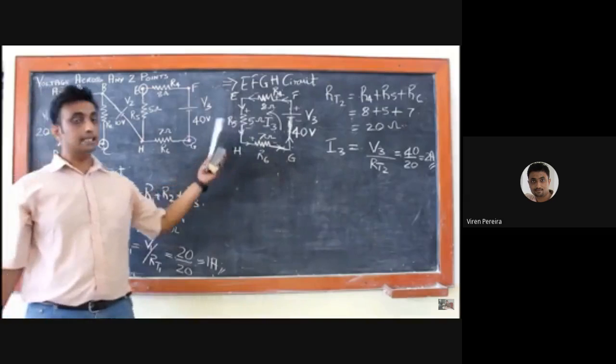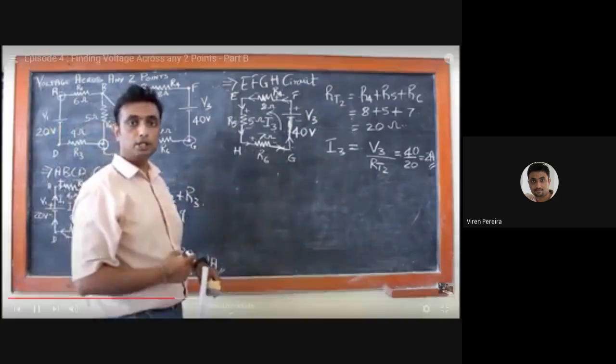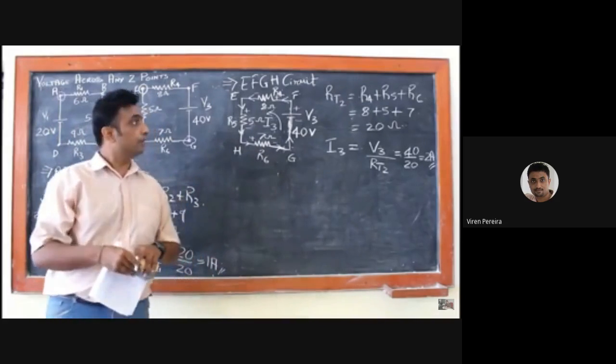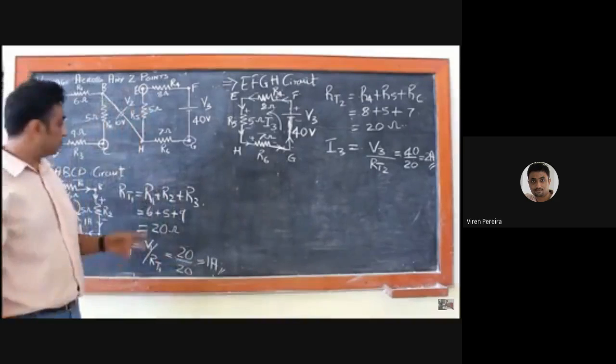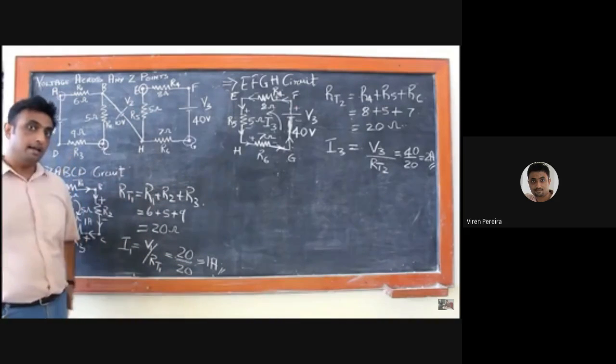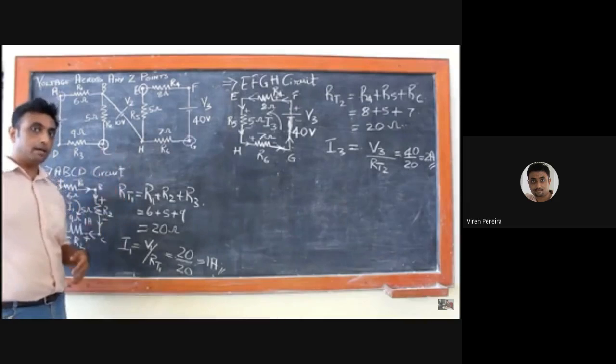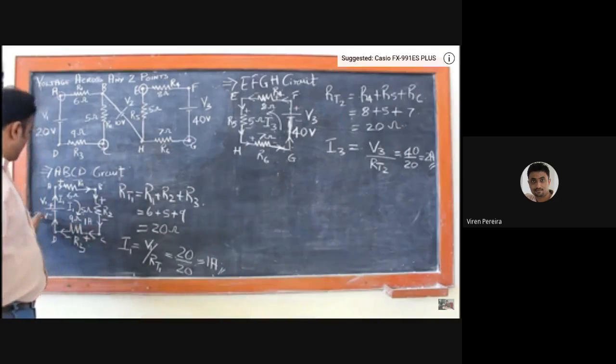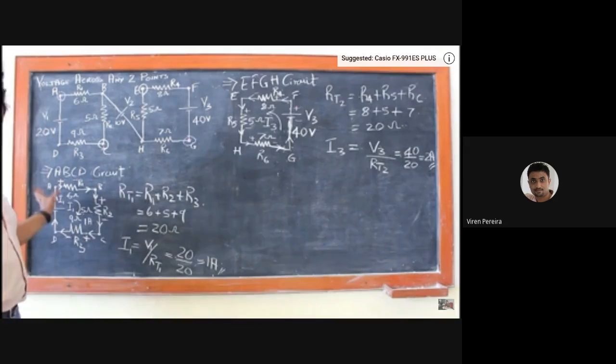Now this is basically using a simple fundamental known as Ohm's law. But you could even go for KVL and also solve this circuit. If we solve it through KVL from the shortcut method, which I have already explained later, it would be voltage sources on one side and drops on the other side. So it would be 20 volts.